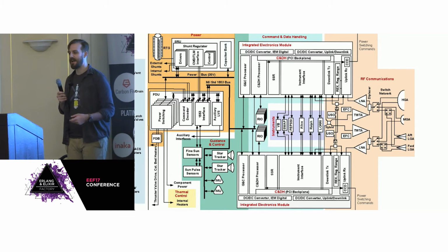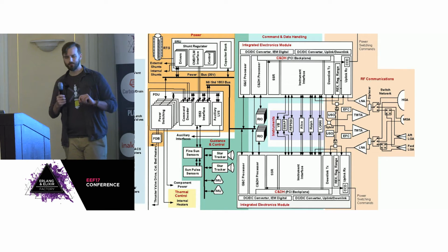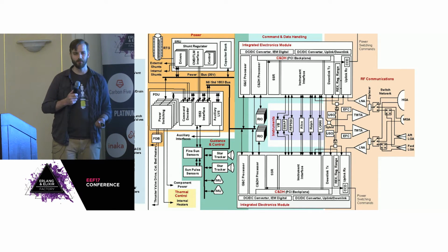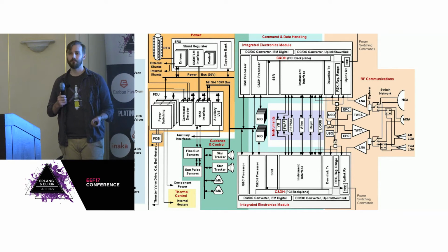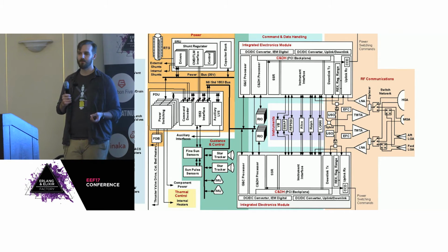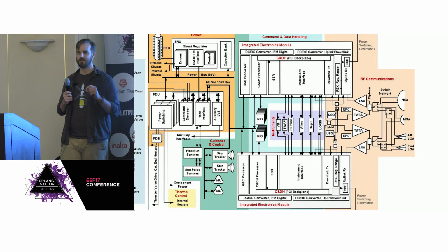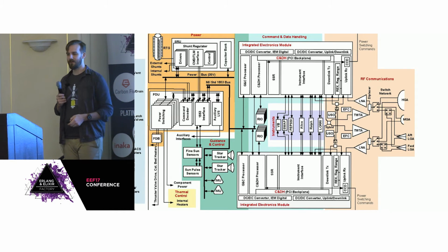It sends information back, and the guidance and control subsystem. Because New Horizons was so horrifically expensive, and because you can't go out and repair it if it should fail, each one of these computers is redundant. So there are actually 4 computers, 2 CDNH and then 2 GNC computers. And they're able to detect failures by analyzing the bus. As I understand it, there's a tiny little microcontroller sitting in the middle of each one of the buses detecting signal degradation, and they flip them off.